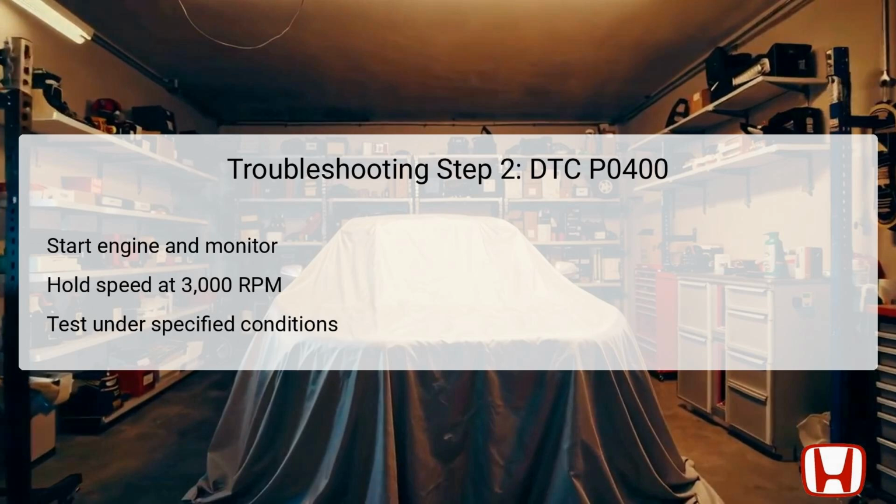The vehicle should then be driven at a speed of 25 miles per hour or 40 kilometers per hour for a minimum of 5 minutes, followed by maintaining the speed at 26 miles per hour or 41 kilometers per hour, with the engine speed between 1,500 to 3,000 RPM for at least 10 seconds, ideally using cruise control. Monitoring these parameters helps assess the EGR system's effectiveness and airflow dynamics during operation.